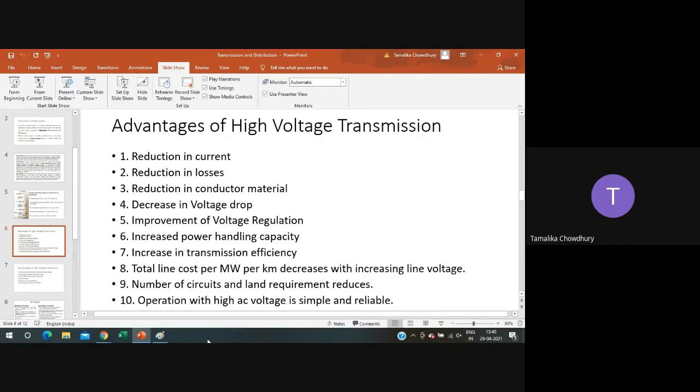That term also shows that line efficiency is higher for higher transmission voltages, because in all the expressions, voltage comes in the denominator. Whether the parameter is line drop, voltage regulation or current losses, V comes in the denominator, which means inversely proportional. Every parameter is inversely proportional to V, and hence the line efficiency is higher for higher transmission voltages, provided constant values of rho, L, J and all other parameters.